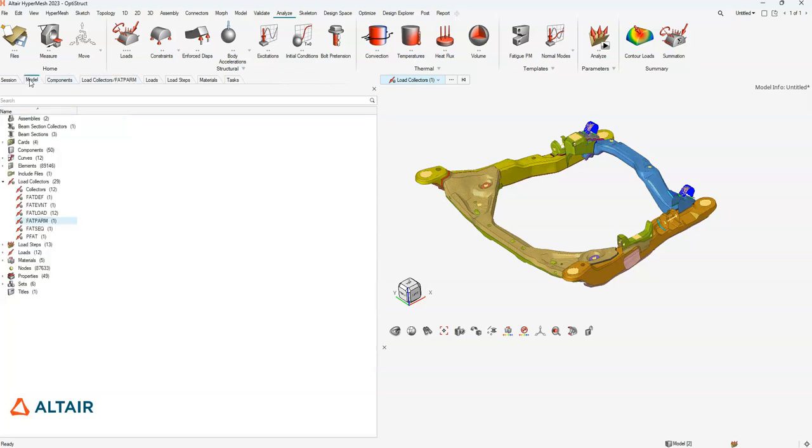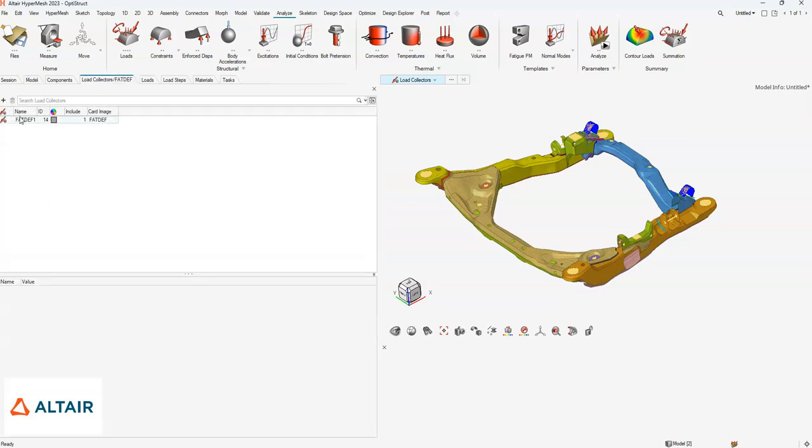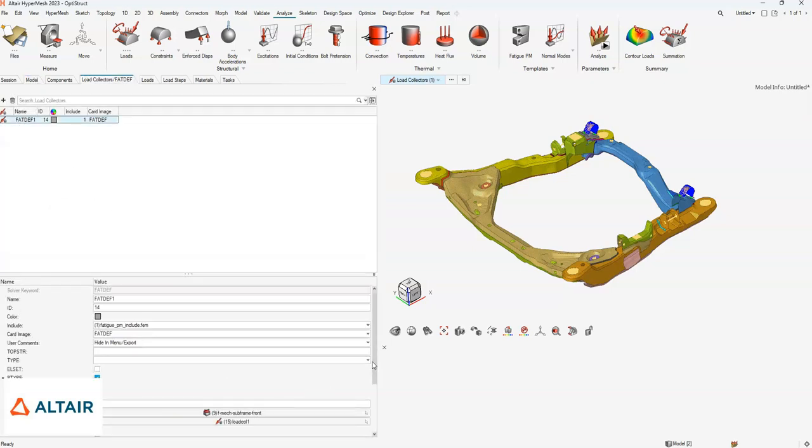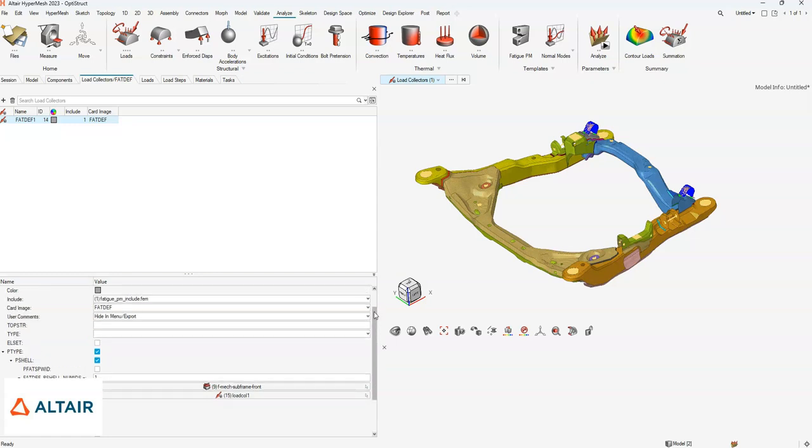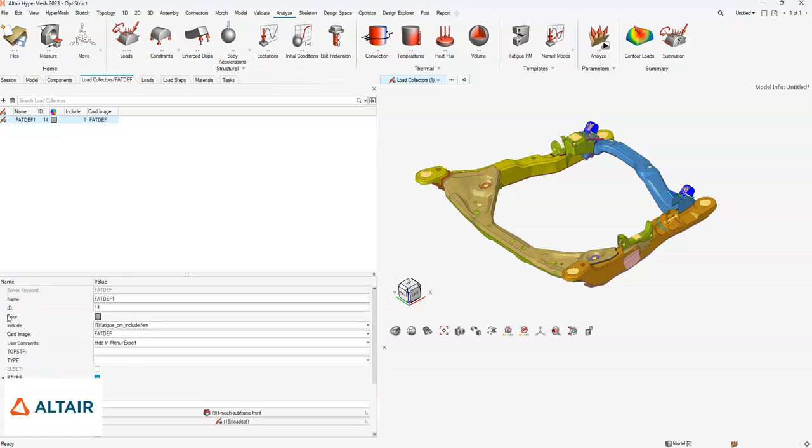Once you go here, fatigue definition is another one that you can check. Here you can see the top stress fraction: elements with combined stresses not in the top fraction of each MATFAT group will be screened out and have no results.